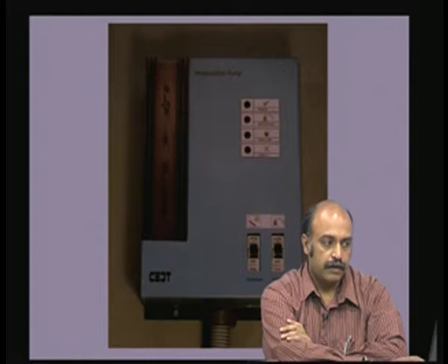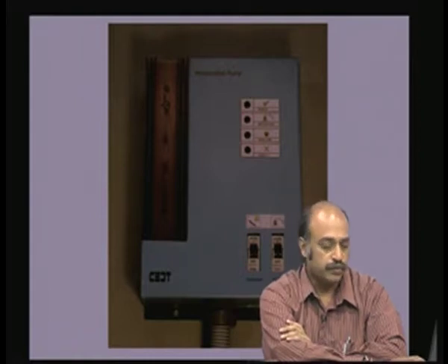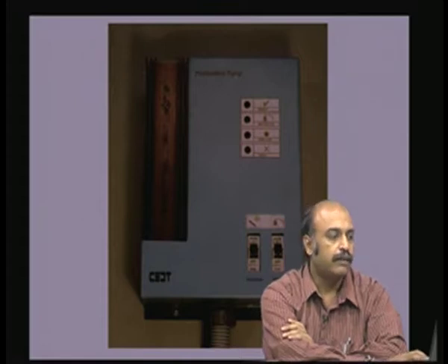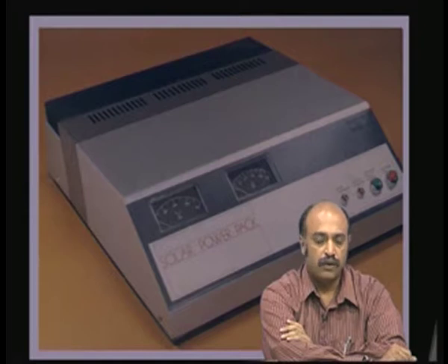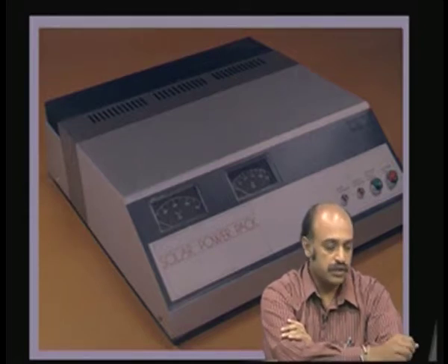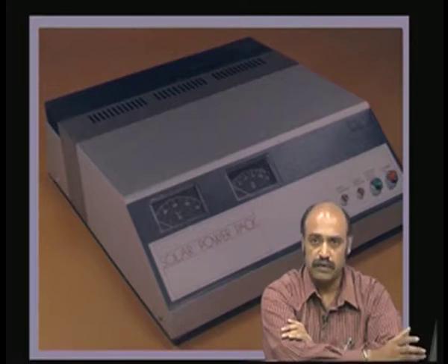The photovoltaic pump finds a lot of useful applications and is quite competitive also with respect to the regular pump. Another useful application is a standalone solar power pack where the input is the solar PV and the output is 230 volts, which can be used to drive any home loads.